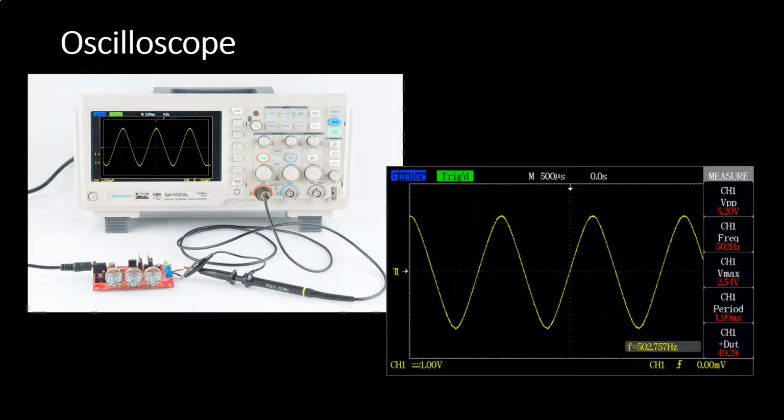The oscilloscope is a device that is used to measure the changes in voltage over time. And in this case, you're seeing in the oscilloscope an AC signal that is being measured from the circuit in the lower left corner of the screen. This is the output that we normally look at when we look at audio, because we're looking at audio as voltage, usually changes in voltage, and therefore we see it going above and below that center line, which is your 0 point.